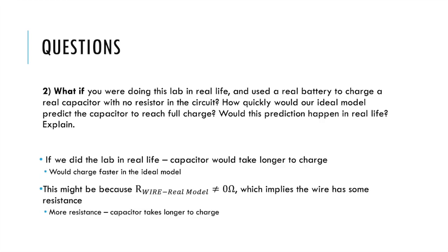So if we did the lab in real life, my prediction would be that the capacitor would take longer to charge than in the ideal model. And this might be because the resistance in the wire for the real model might not be equal to 0 ohms. So this means that the more resistance, the longer the capacitor takes to charge. As well, the battery might have some internal resistance as well.